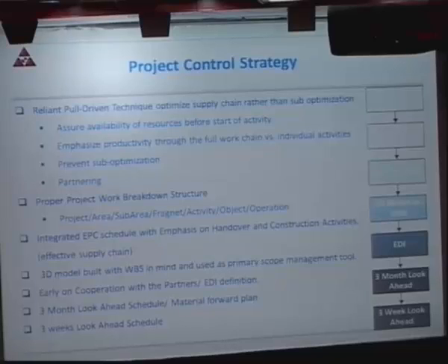Again, I believe that the most important exercise that you do is the 3-month look-ahead schedule. If you do a detailed 3-month look-ahead schedule, you will have good work on site. If you don't, nothing will happen. We will still have the same problems you're having now. Use BIM tools, not Primavera. Detail more, go to the level of the object and the operation. And then for site coordination, you need a 3-week look-ahead schedule.